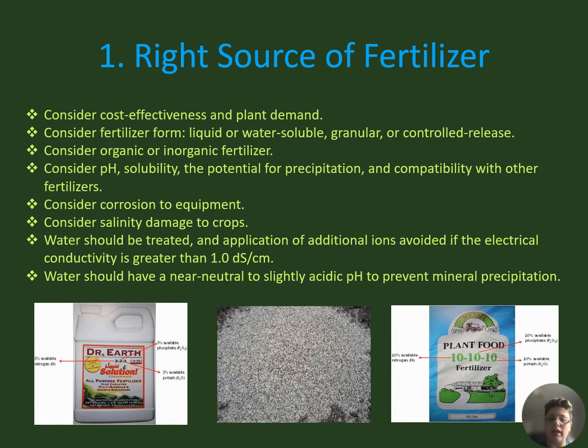Water should be treated and application of additional ions avoided if the electrical conductivity is greater than 1.0 dS/cm. Water should have a near neutral to slightly acidic pH to prevent mineral precipitation.